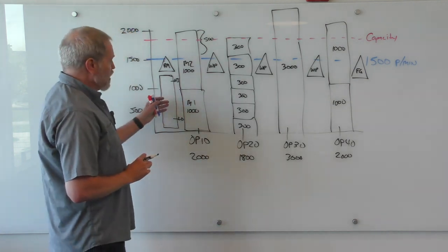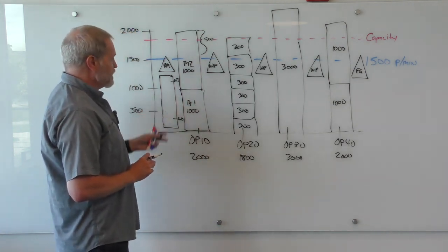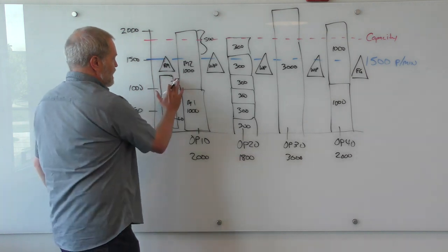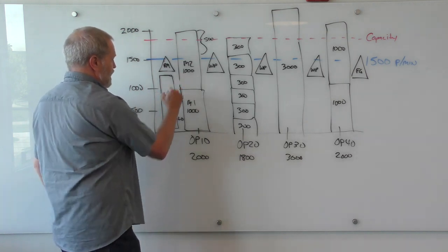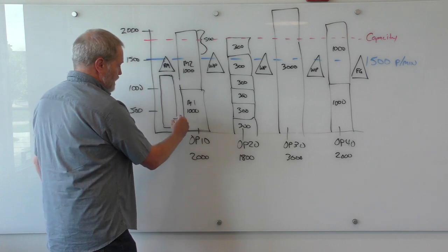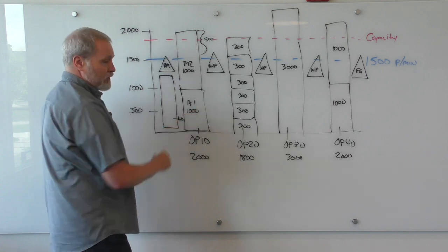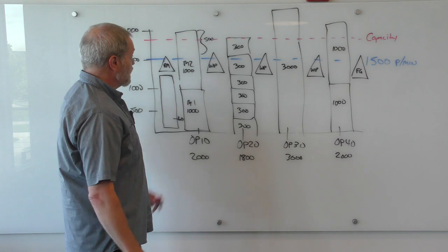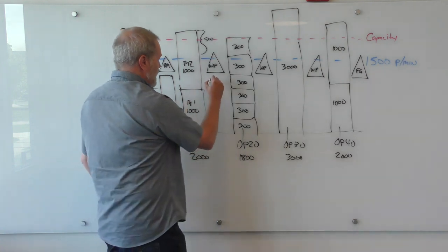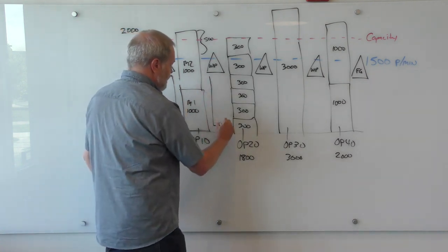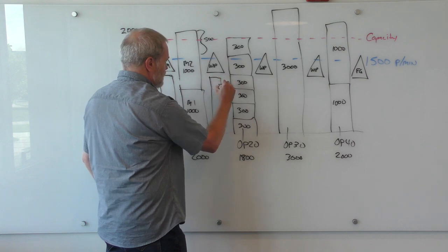For this first raw materials side, there is no risk of blocking, so there really isn't necessarily a high limit there, but we do care about the low side of it. If we run out of raw material, I can't produce. I'm starved to be able to run. As we move down the line, we actually have a high and low for each one of these.